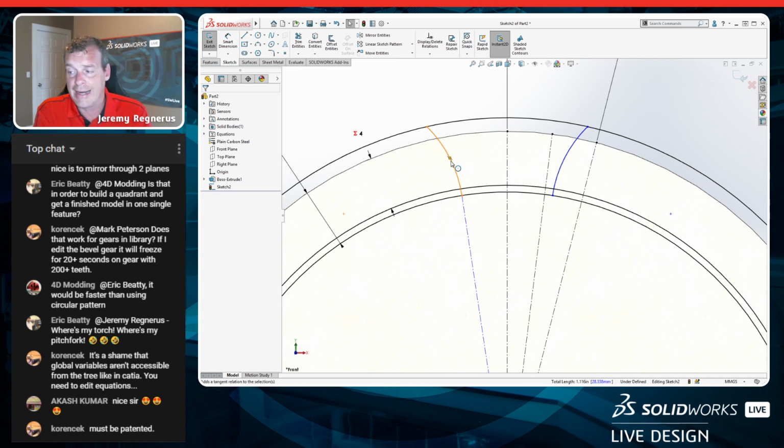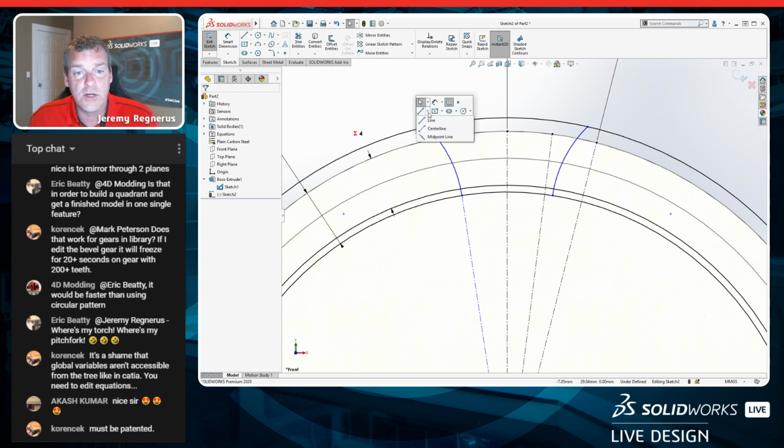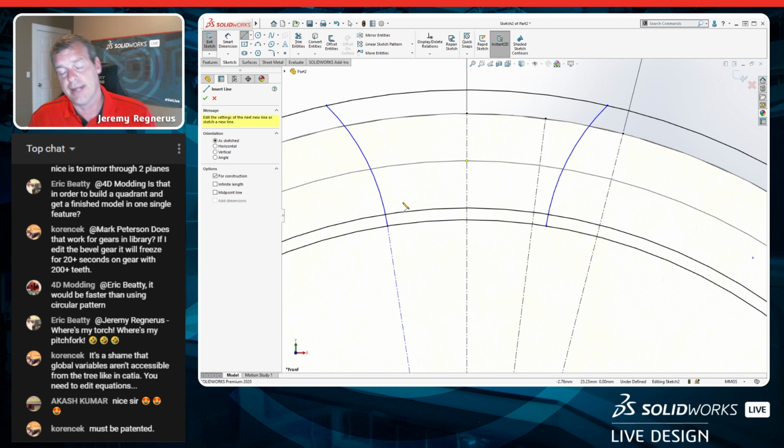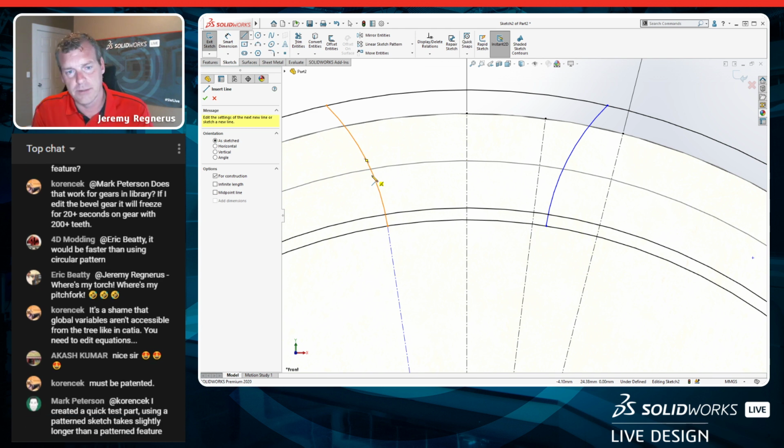We're going to go back and access that sketch geometry by simply going into the feature manager tree, and you can see here I can expand this extrude and I can show that. This is geometry that I can use whenever I want, and I'm going to reference it here. We're going to create a horizontal construction line, and I'll talk about why we're using a horizontal construction line as opposed to the chordal arc length in just a second. We're going to create a horizontal line at the intersection of those 2 points. Notice when I hover over this line next to my cursor, I get a little yellow icon.